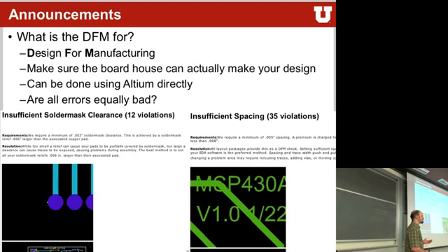What that's usually called is tenting. So oftentimes for vias, if you look at actual PCBs, sometimes you can see via holes that go down, but they have solder mask on top. What they did is they tented these vias with solder mask because they know they won't solder to them, so why not just tent them over? The boards look nicer, and you also have less chance of shorting. At the same time, again, you can't probe your board anymore at these spots. If they're actually open, you can take an oscilloscope probe and just probe the signals that go through. So there's a trade-off that you sometimes have to make.